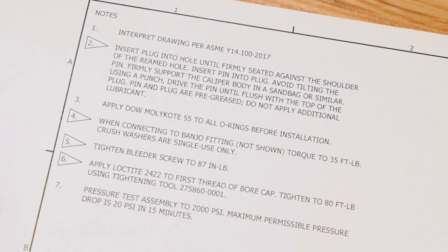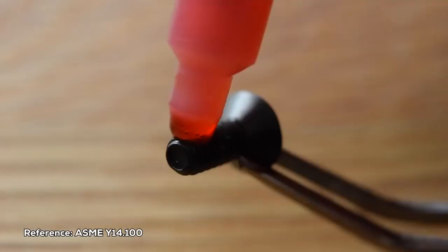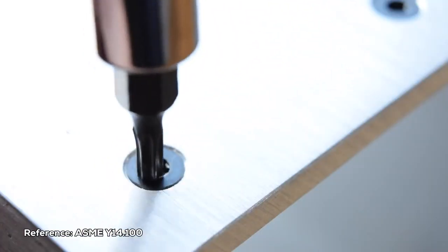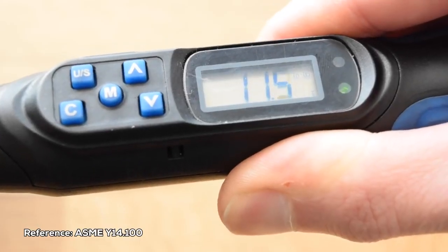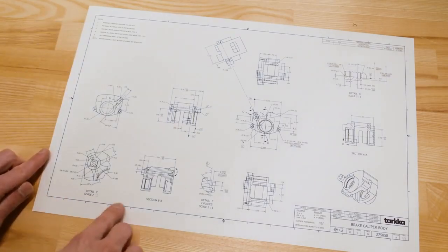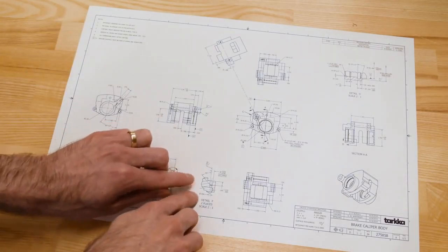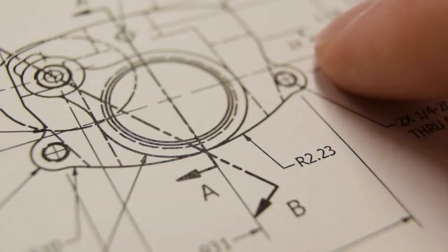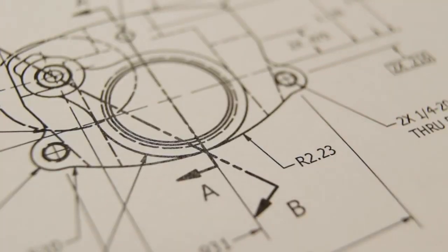The notes list provides information like the material and coating specifications, relevant standards needed to interpret the drawing, special instructions for manufacturing certain features, and other information that can't be conveyed with a dimension. The border defines zones with letters and numbers that allow you to identify specific features with coordinates. This is really handy on big drawings because you can say something like change the 0.19 hole diameter in zone A7 and be able to jump right to it, instead of having to scour the entire drawing to find something.